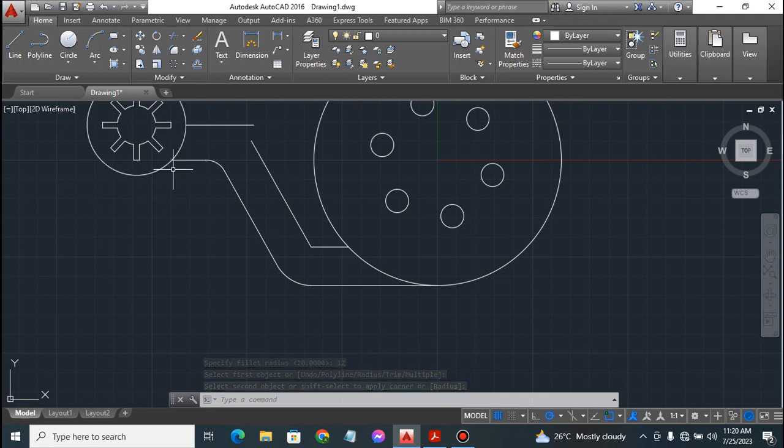Right at this point, we also need a curve, not a straight edge. It's not straight according to our PDF document, and the fillet radius there is 10 millimeters. So using the same approach, click on the fillet tool. Here is where my cursor is right now. Click on it to select the fillet tool, then type in R for radius, then type in the fillet radius, which is 10. Press enter on the keyboard. Click on the edges you want to convert to a curve. All right, that's what we need now. Okay, so that has done it.